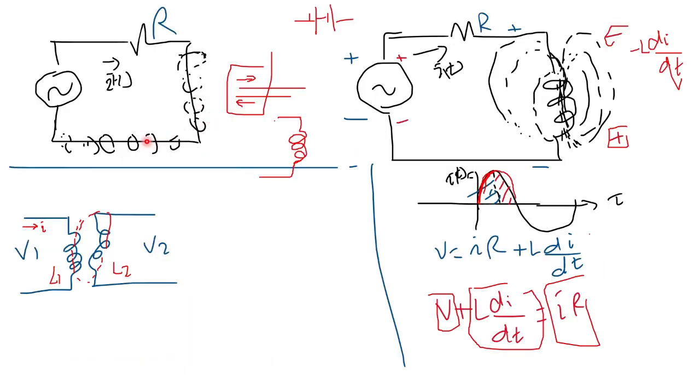Any wire, even a straight wire, having AC or DC current passing through it would have a magnetic field around the wire. This magnetic field can be weakened or diminished, for example, in the case of a twisted pair. If we use a twisted pair like for electricity in the houses, one wire has current flowing in one direction, the other wire has the current flowing in the other direction. The two resulting magnetic fields will cancel each other.